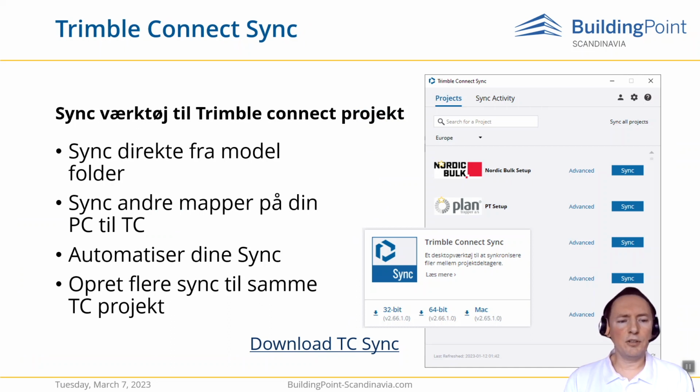It can synchronize folders directly from your computers to the cloud. That can be some folders in your Tekla model you need to synchronize up. It can be some other folders on your computer with other stuff belonging to this project that you need synced up so it will be shared with all. It can be set up to sync automatically, so you can sync once a day or every hour or whatever you need. And you can also set up multiple syncs, so you can sync from different places and many times.